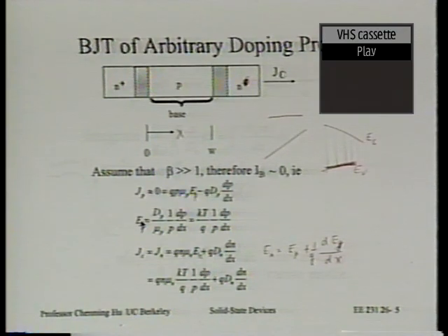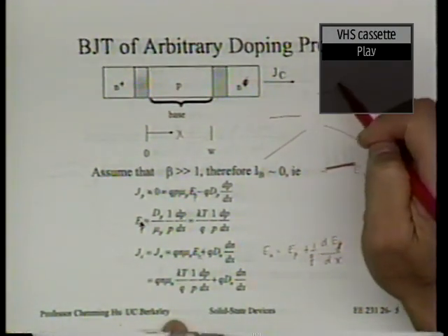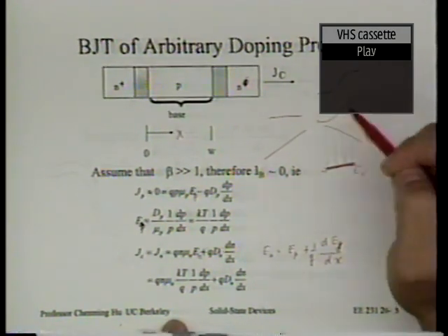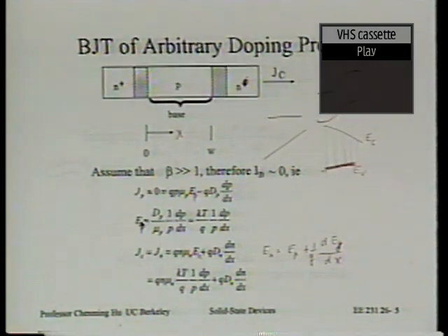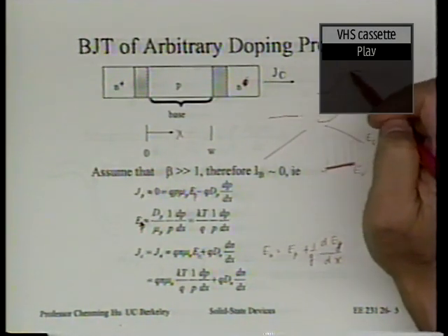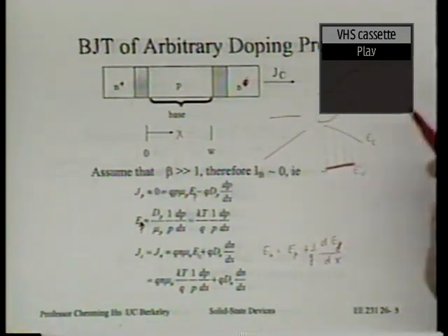Also, I just don't really understand. It's like there's two different electric fields. What does that mean? This is the same thing as when you have a built-in potential in a p-n junction, for example. You may have thought about this. What's the meaning of this built-in potential? Is this something you can measure? You cannot. You put a voltmeter there, you won't be able to measure that. It's not there. However, as far as an electron is concerned, it certainly sees a lower potential at one side, higher potential on the other side, so it's going to move.